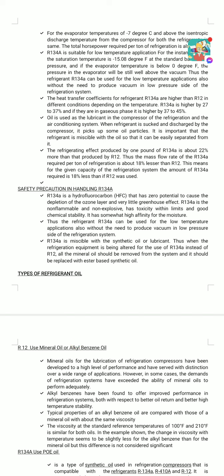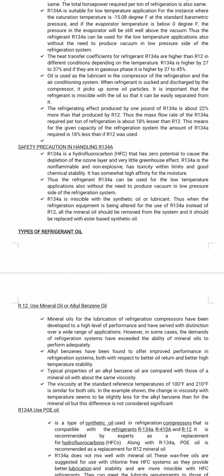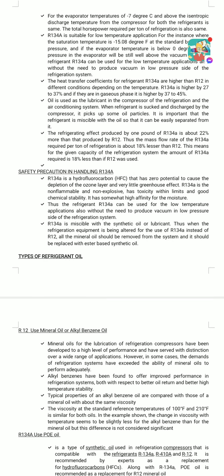Thus, the refrigerant R134A can be used for low temperature applications also, without the need to produce vacuum in the low pressure side of the refrigeration system. The heat transfer coefficients for refrigerant R134A are higher than R12 in different conditions depending on the temperature.